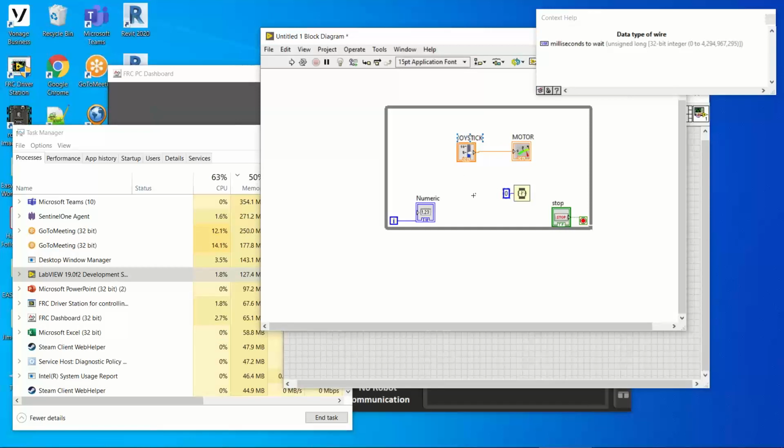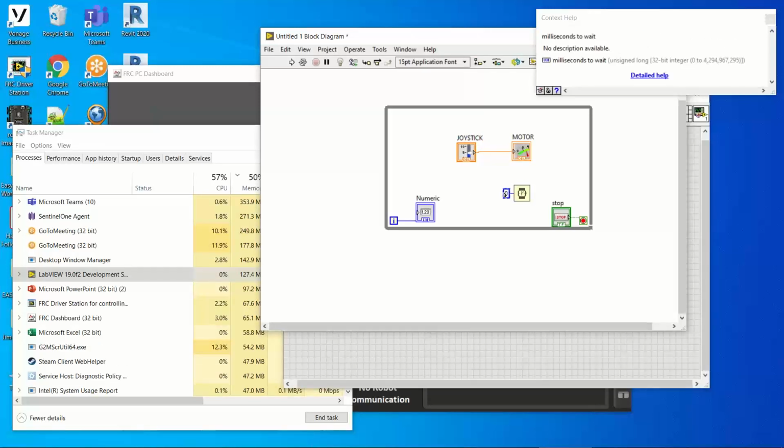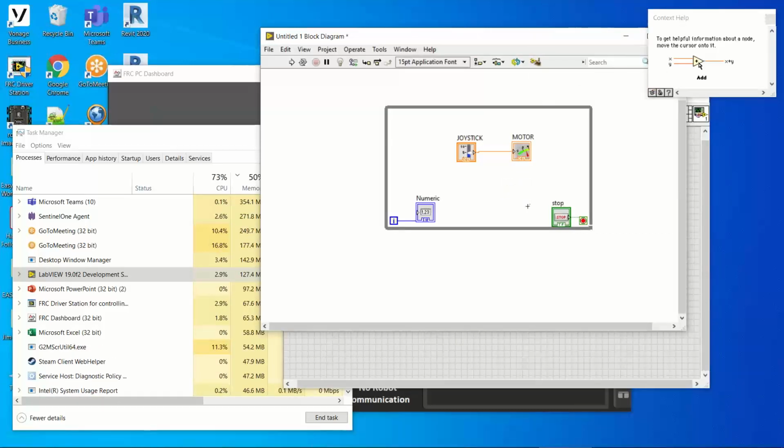When we get into robot controls and logic calculations, and checking sensors, I reduce that down to 10 to 20 milliseconds, but never, never, never do I want to have a 0, or worse, do I want to forget to put a wait stage in there, because it sucks my processor bandwidth down terribly.